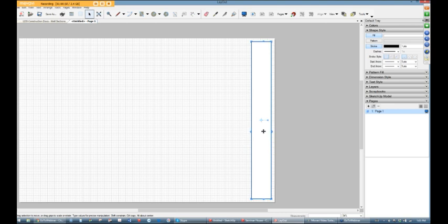That particular fill is solid. And I may not want that. So in the shape style, there's a fill button at the top. And you can see it's blue. That means it's turned on. And it's white. So it's showing white. If I turn it off, the fill button is turned off. You can see the grid through there. So right now there's no fill. There's basically just essentially a rectangle. And you'll notice that when I draw that, it connected itself. It's one single box now. It's not a bunch of lines.